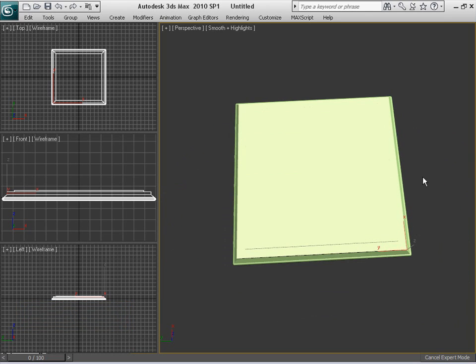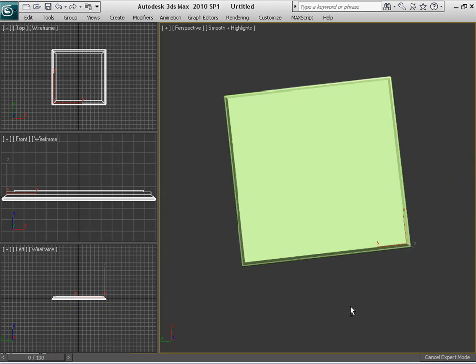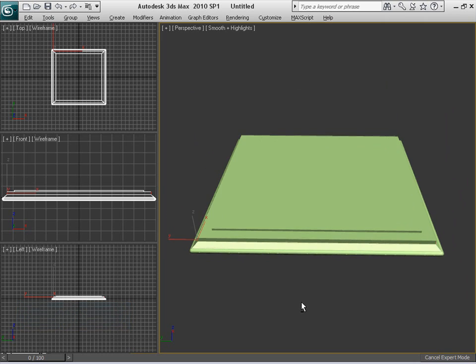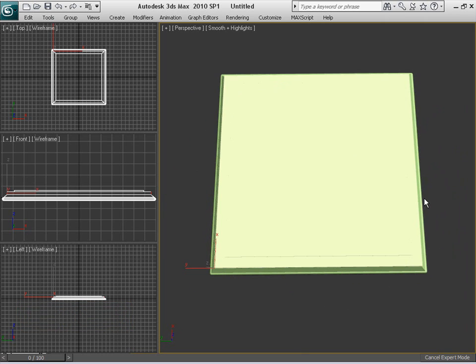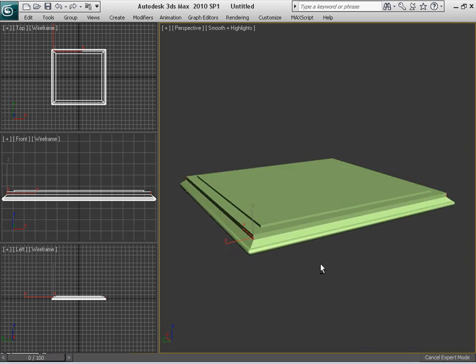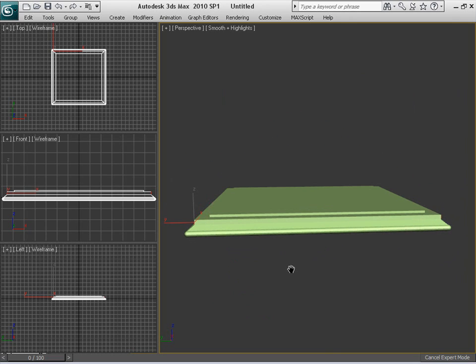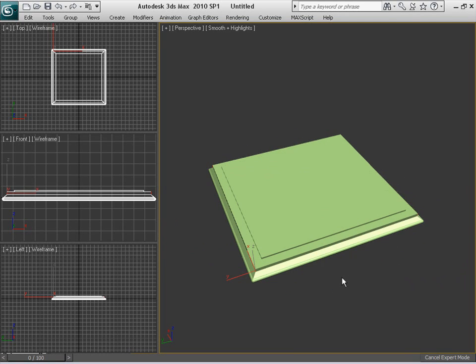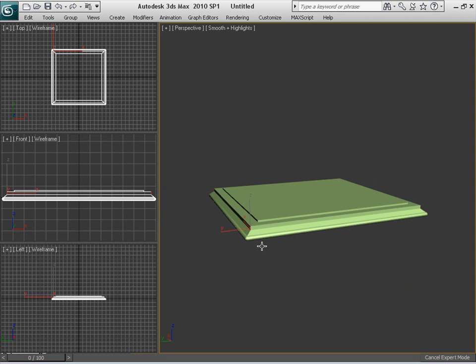and in this case I want to select the 4 edges around the box, and there's a cool command that we can use for this. We're going to hit Alt R. What this does is make the selection in a ring form, so it is gonna select the 4 edges at the same time. This works for faces, vertices, and it is very useful. There's another command that is Alt L, which makes the selection as a loop. That is another way that maybe we will be seeing later on, but it is good to have this in mind.